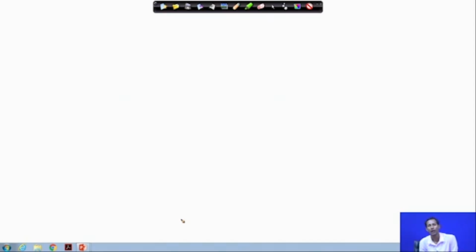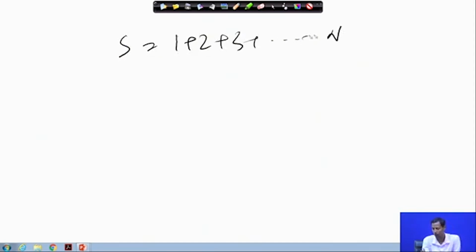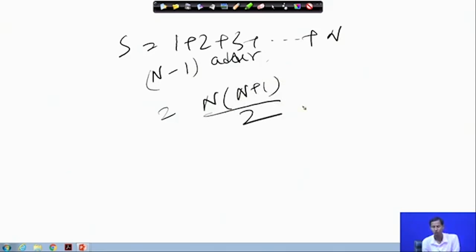We have seen another example, that is the sum of n natural numbers up to n. Okay. So, what I said is that for this I require a parallel implementation that requires n minus 1 adders, and another implementation technique is that this expression I can also write as n times n plus 1 by 2. So, here I require one incrementer and one multiplier block. So, when this n value is large, at that time this will also give you the parallel implementation.